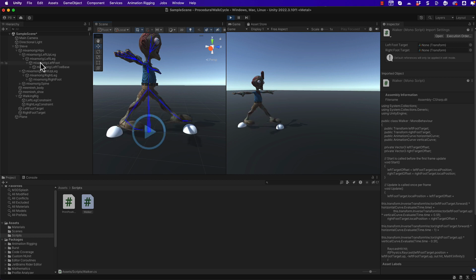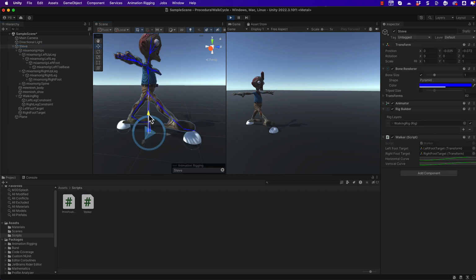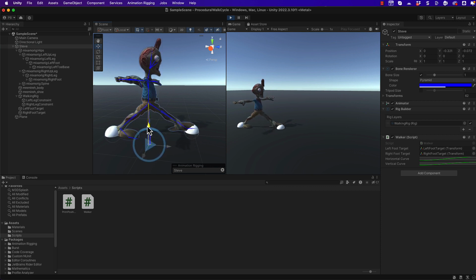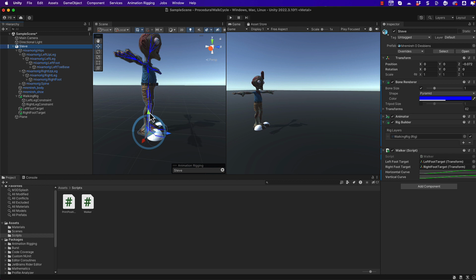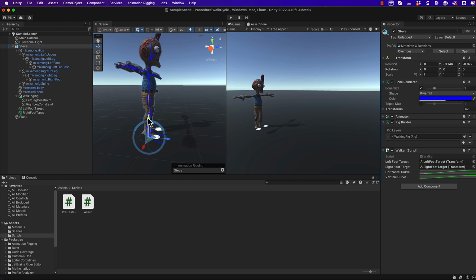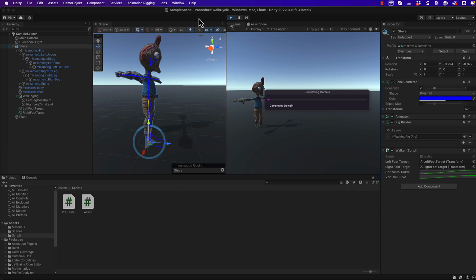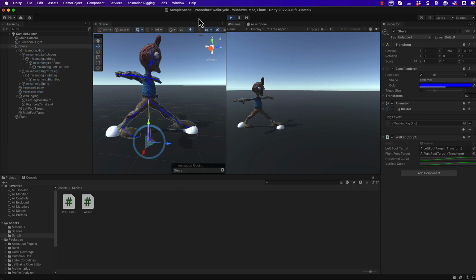Now, the nice thing about this is if we get Steve and actually move him down, then we now get movement in our knees, because you see that the spheres are now sticking to the ground, which gives a more realistic walking movement, because that's what happens when you move. Your knees bend and you're actually touching and moving your feet along the ground. Okay, so let's stop playing. At this point, you could grab Steve and move him down just a little bit. So now the spheres will snap up onto that surface and we will get a nice bend in the knees as we're walking.